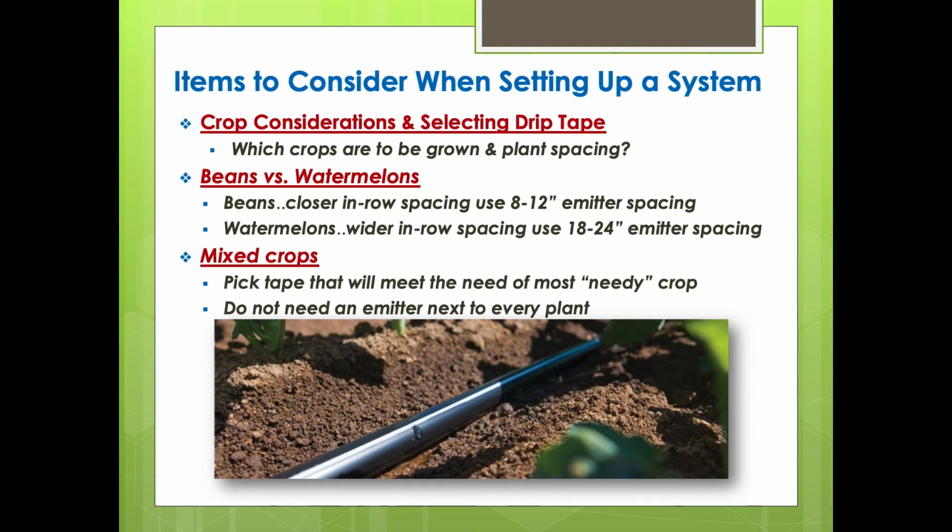The reason is that if the drip tape is laid out correctly and you have nice firm beds out there, you will get lateral movement of water. You'll get water that moves across the bed, not just down. That's key in the bed formation process, to make sure that's done correctly, so that you get good water movement across the bed.